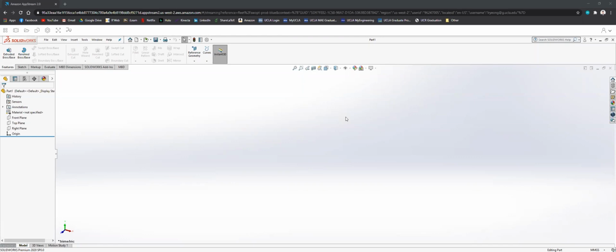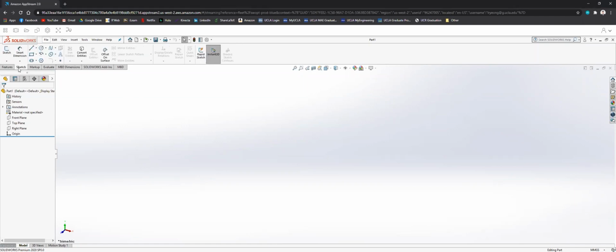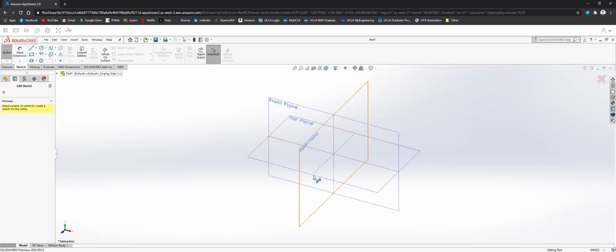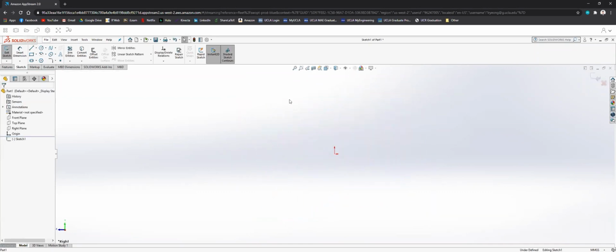And first off, I'm going to create the wheel. So remember when you first enter SolidWorks, you have to look at your units. In this case, I'm using MMGS this time, millimeter gram second, on the bottom right. So I am already in a part section, so I'm going to create a sketch on the right plane. I can click on any of these planes, I'm going to click on the right plane, and it's going to adjust automatically.